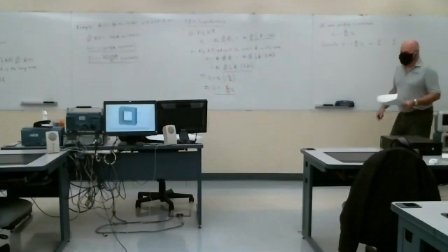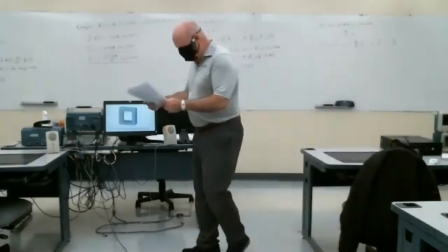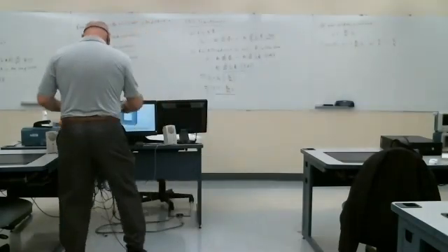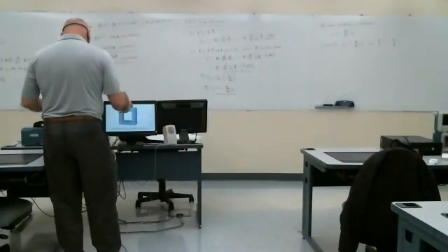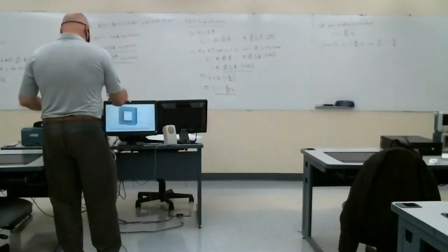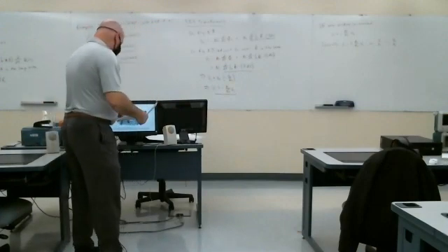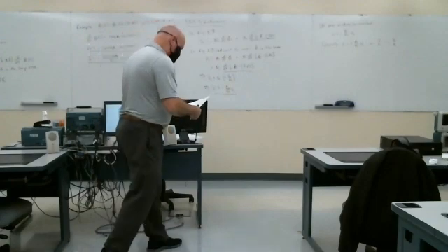So visualize the source connected to the primary. We did that. Determine the flux direction from the current flowing from plus to minus, treating that as a load. Then imagine opposing flux in the secondary and the corresponding current direction, with the current flowing from minus to plus. Then if the polarity matches the polarity assigned to the secondary, use the plus, which is correct.